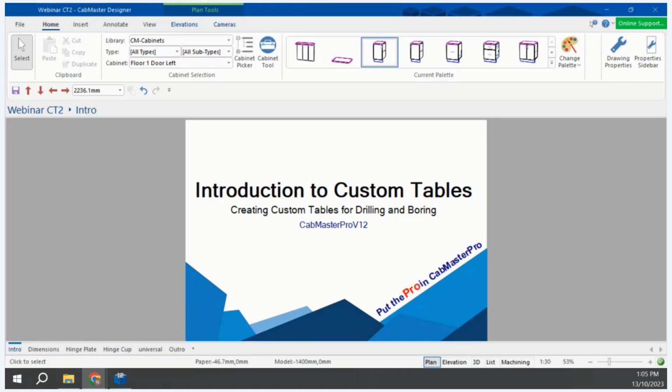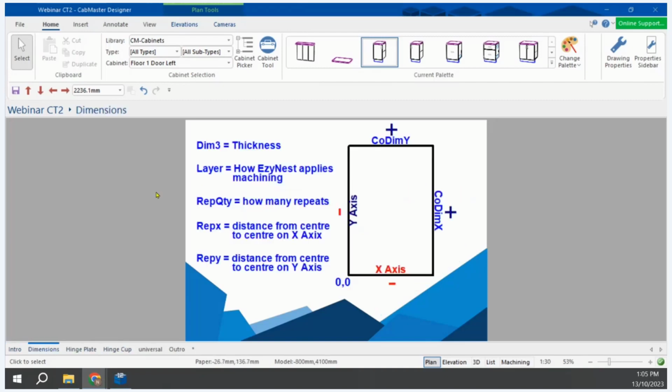To start off, let's just add a circle to a left end. Now there's 2 ways to do this. We could apply a shape and radius the edges, similar method to last week with the rebate. We can plot each corner with X and Y values.